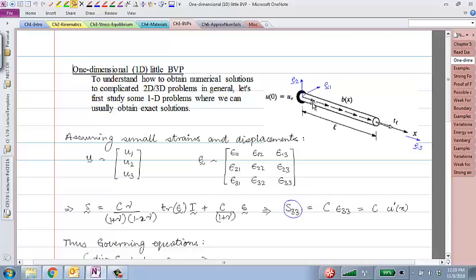So we are going to look at this three-dimensional bar with a circular cross section, some traction applied on the end face here, and some body forces acting on it. Body forces are distributed forces per unit volume. Think of a flexible rubber bar hanging from the ceiling, with an end load applied at it. The body forces represent the self weight, and TL, the traction at length L, is the external force applied to this.